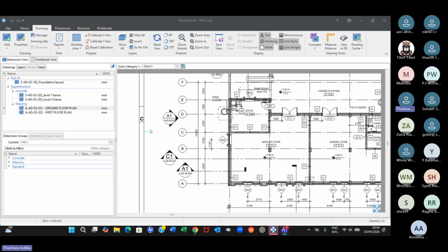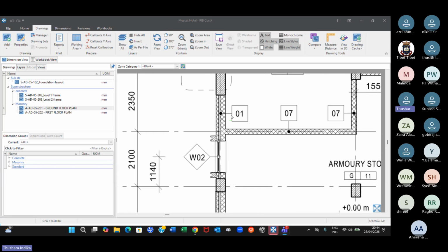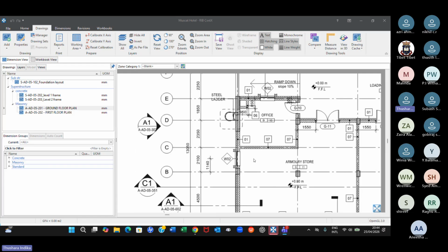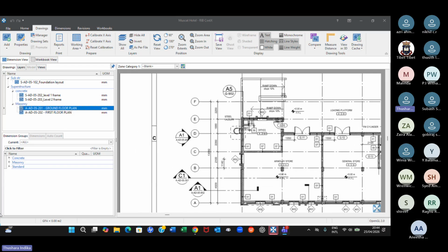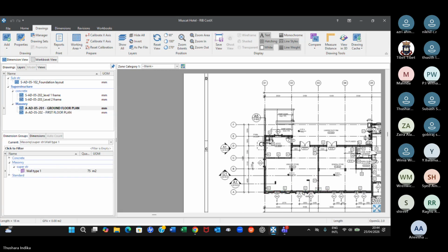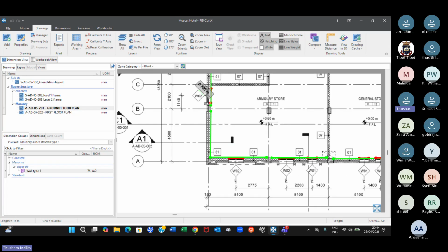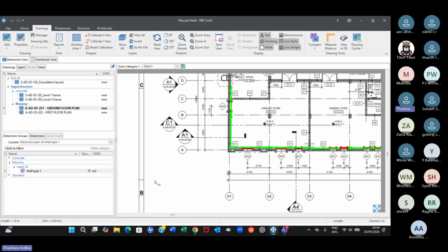Last week we measured type T1 blockwork, type 1 blockwork in other words, and then we produced the 3D view also. This is the masonry superstructure that we have measured. Then I explained how to deduct the windows, like what we did with the slab thicknesses, where we measured 250 millimeter thick in method 1 and then deducted the negative dimensions.